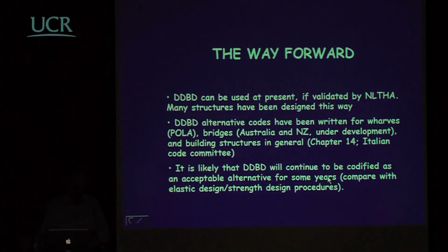In other words, we don't expect it to replace force-based design, but to be a parallel design approach, so you can use either approach. It's also worthwhile noting that displacement-based design can be used at present in most seismic design codes if validated by nonlinear time history analysis. So most codes will say you should design this way, or if you use something which is non-standard, you must verify by nonlinear time history analysis that the drifts aren't exceeded and that the ductility demand of individual members aren't exceeded. And this is how structures have been designed so far. Quite a few designed using nonlinear time history analysis to verify direct displacement-based design.